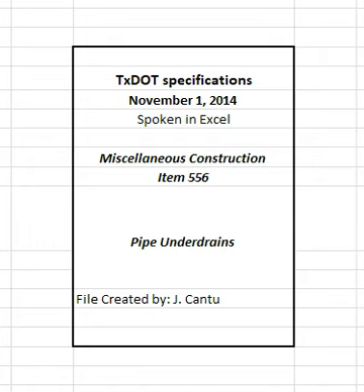2.1.7 Type 7. Corrugated polyvinyl chloride, PVC, pipe conforming to ASTM F949. 2.1.8 Type 8. Smooth wall PVC pipe conforming to TxDOT M278, Class PS46. 2.1.9 Type 9. As shown on the plans.